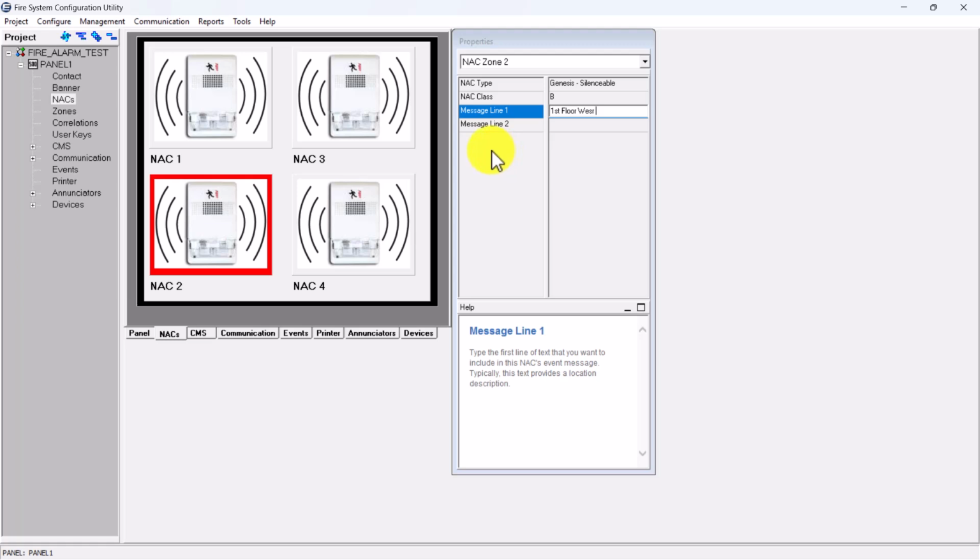So now that we have our modules addressed and labeled, when you look over here to the right side and you're going through your drawings, because the electrician gave you the drawings with the serial numbers, each one of these devices, you will put the serial number inside of this box here. So that way it knows that this relay for fan shutdown is whatever that serial number is. So you put all your different serial numbers inside of the serial number box for each and every device.